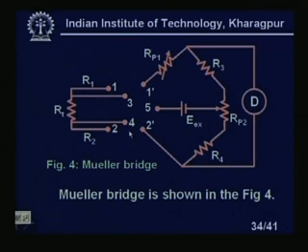And you see that the potentiometers are RP2 and RP1. RP1 is the one we use to balance the bridge, and RP2 is purposefully not used once it is set. It is used to make the resistance of the right hand side of the bridge total R3.